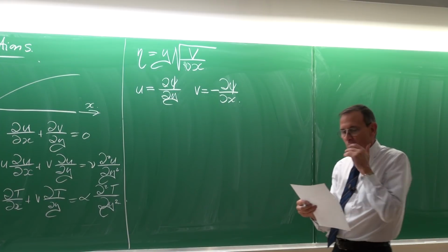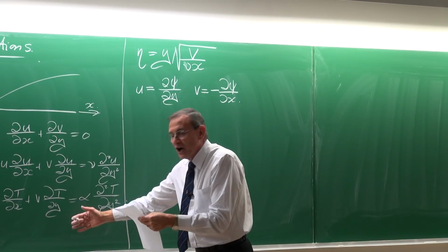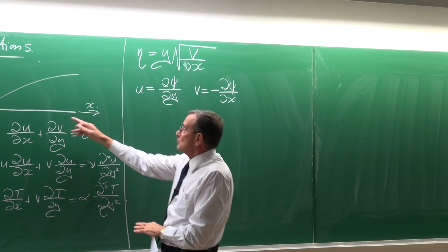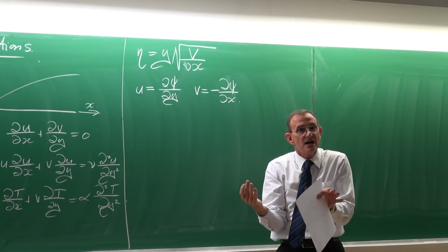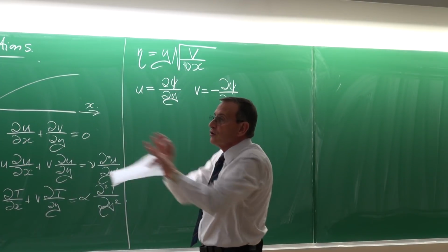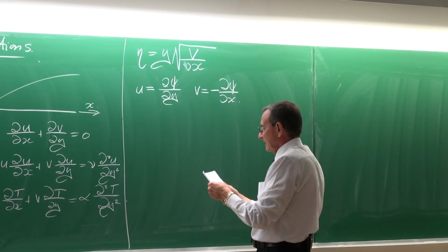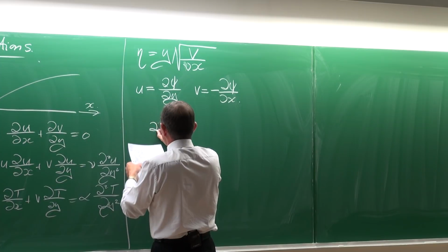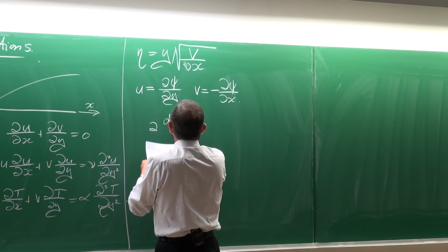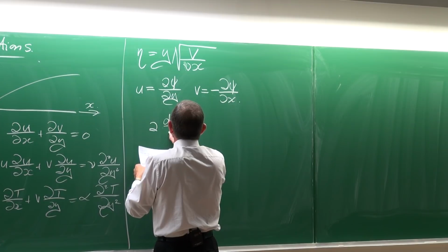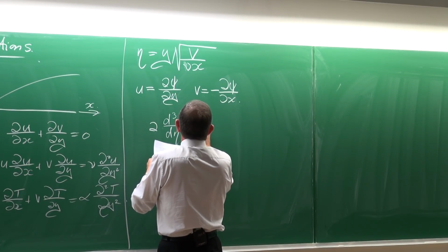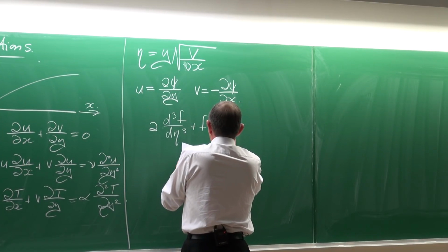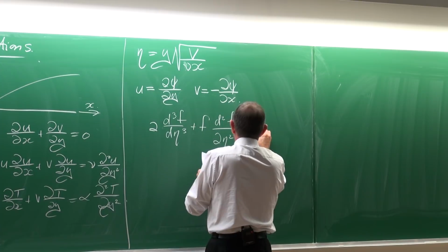Then he figured out that these three equations with three boundary conditions, where of course the velocity on the walls is equal to 0, and a similar thing for the thermal boundary layer, he would use all that, and then he came up with a third order differential equation, which was 2 times d3f/dη3 plus f multiplied by d2f/dη2 is equal to 0.